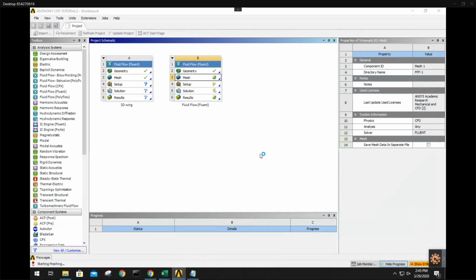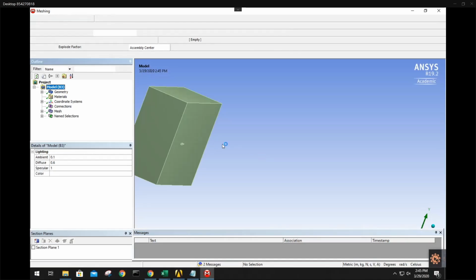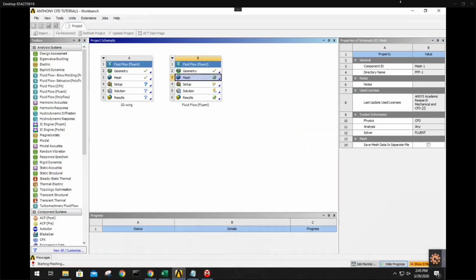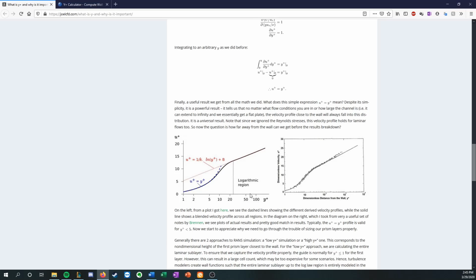Basically, for a two model simulation, K omega is generally the best. Wall functions approximate everything. That's the thing. So they approximate all of this, when in reality, K omega can solve for this complicated region and then switch to something like this farther away. That's actually what the K omega SST does: it focuses on this, and then it switches to a wall function farther away.